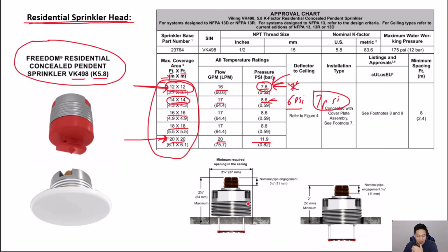And depending on your job, if you need a higher throw, then you would use a different value in your hydraulic calculations, based on that sprinkler head, if it happens to be the one that requires the most hydraulic demand, okay, which generally is the highest and furthest away from the source, but not necessarily.